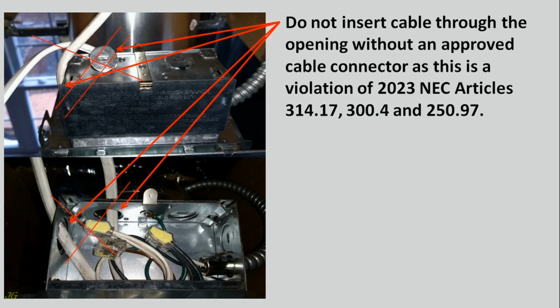Do not insert cable through the opening without an approved cable connector, as this is a violation of 2023 NEC Articles 314.17, 300.4 and 250.97.